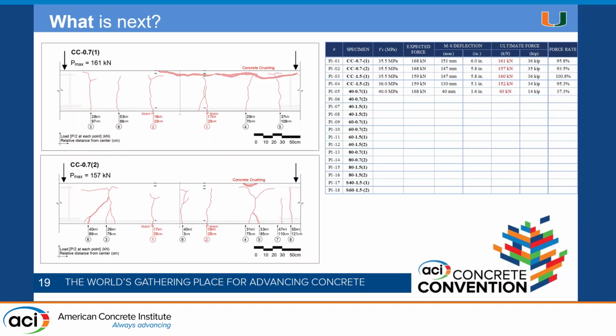So if you have more or fewer cracks, that will affect the way the bond is working, and of course that affects the effective development length. Usually in previous studies, when they compute the bond stress, they just take the average. It's a reasonable way to do it, but it doesn't take into account the real behavior and the real mechanisms of the bond stresses.